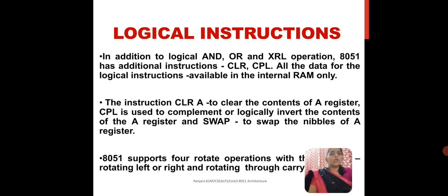In addition to the logical operations such as AND, OR or XOR, 8051 has additional instructions such as CLR, that is clear, and CPL. All the data of the logical instructions is available in the internal RAM.